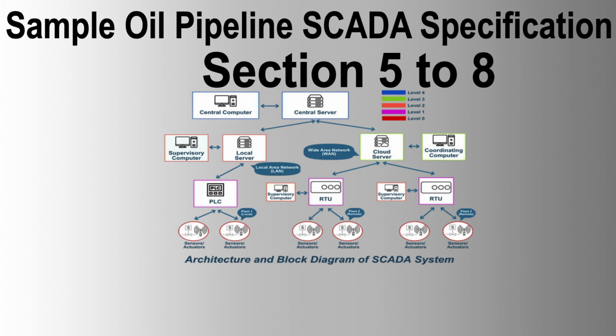6.7.9 Electronic Modules. Electronic modules shall be identified as to type and function on the front panel with a unique serial number. 6.7.10 Printed Circuit Boards. Printed circuit boards of all electronic modules shall be coated with non-tracking varnish, with copper tracks at least 65 microns thick.